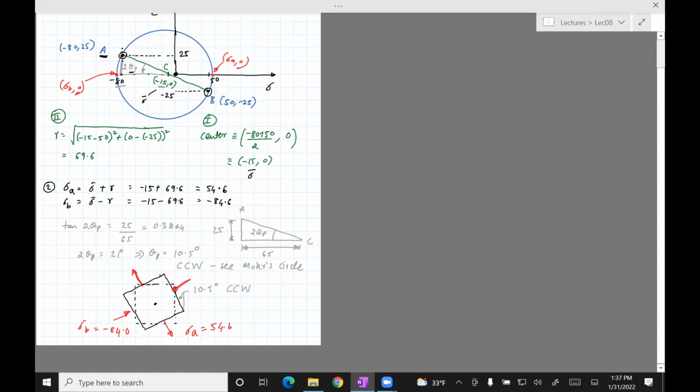So there's no shear stress. You wouldn't show shear stress there because it's that direction of principal stress. Okay, so note that when we did this whole thing, we never ever used that formula which I wrote down. We simply used a grid paper, drew the points, drew the circle, identified the center, radius, and so on.